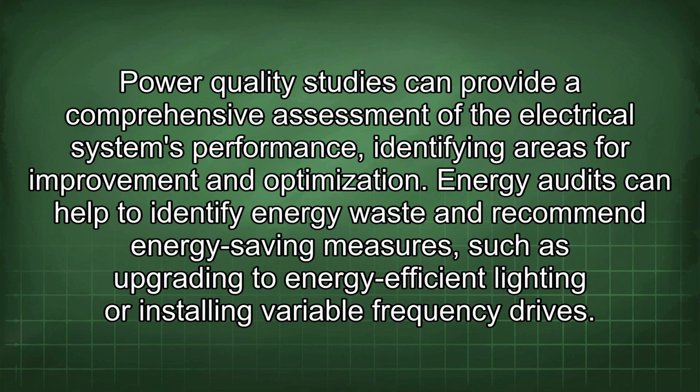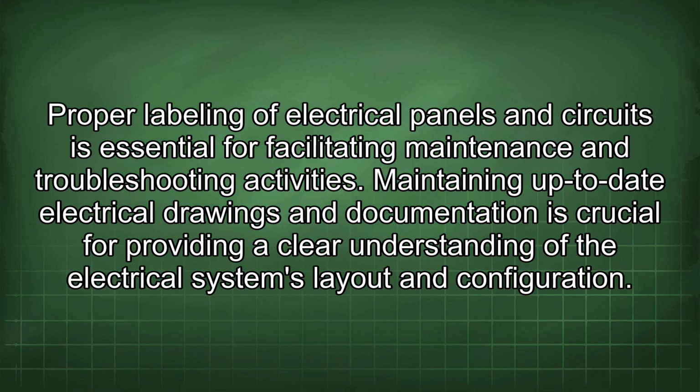Power quality studies can provide a comprehensive assessment of the electrical system's performance, identifying areas for improvement and optimization. Energy audits can help to identify energy waste and recommend energy-saving measures, such as upgrading to energy-efficient lighting or installing variable frequency drives. Proper labeling of electrical panels and circuits is essential for facilitating maintenance and troubleshooting activities.